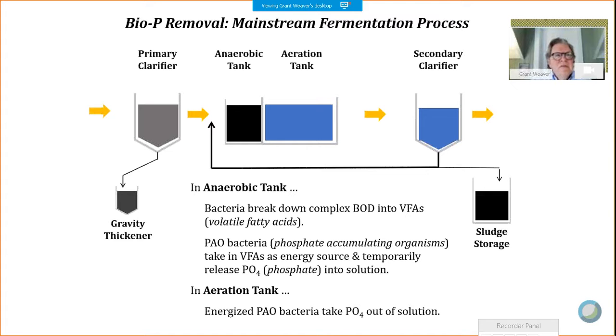Now the phosphorus concentration, if everything's dialed in, is crazy low, 0.05 kind of concentration of soluble phosphorus, which now makes whatever phosphorus is in your final effluent, the vast majority would be as TSS, right? Because if you had a TSS of 10, say, and the concentration of that was like 3% phosphorus, that's a 0.3, and the phosphorus soluble is 0.05.